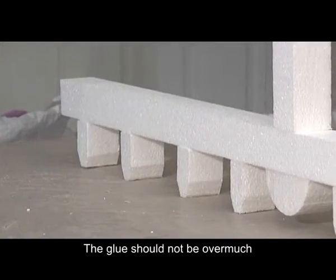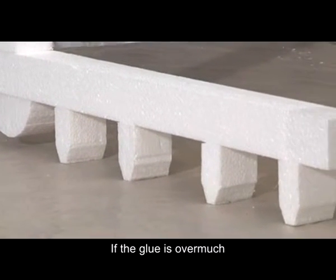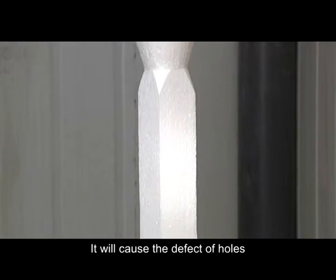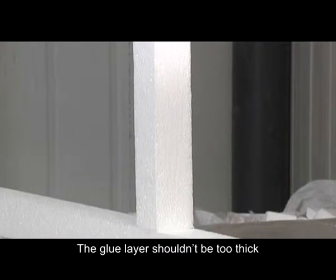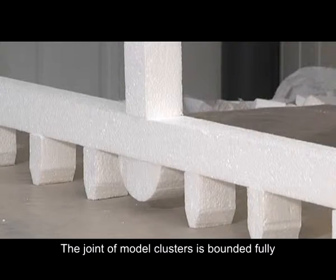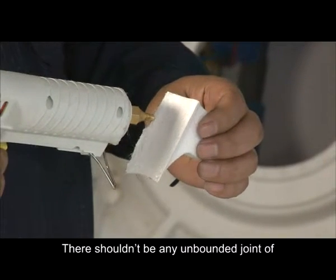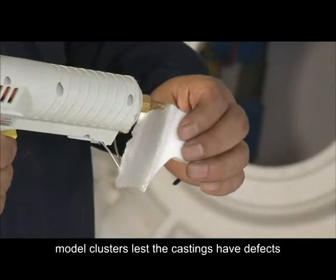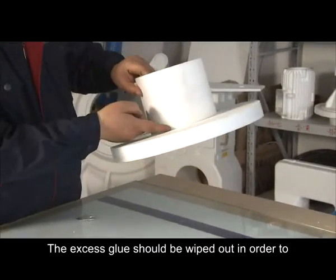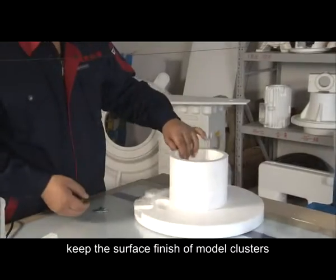The glue should not be overmuch when you glue the model clusters. If the glue is overmuch, more gas will be produced, which will cause the defect of holes. The glue layer shouldn't be too thick, lest the size is not precise. The joints of model clusters should be bonded fully. There shouldn't be any unbonded joint, lest the castings have defects. The excess glue shouldn't be wiped off in order to keep the surface finish of the model clusters.